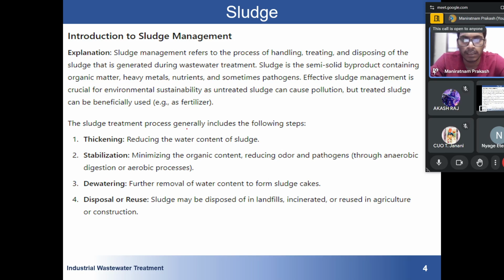Okay now, these are the four treatment processes that are used throughout the world. First we have thickening, that is reducing the water content, because water can be removed and we are more concerned about the sludge, which is the solid. So first we have to thicken the sludge. There are several processes that you have gone through in the lecture on how to reduce the water content.